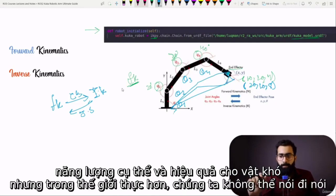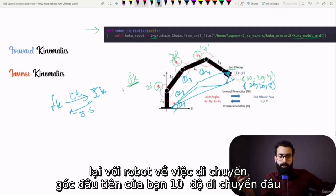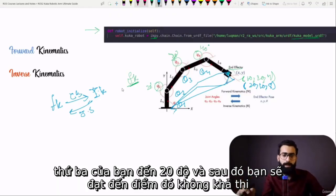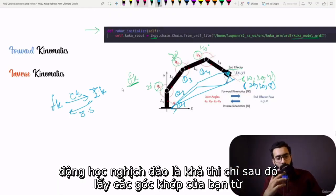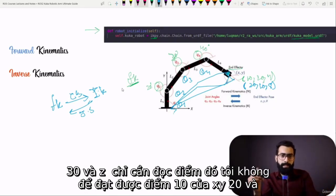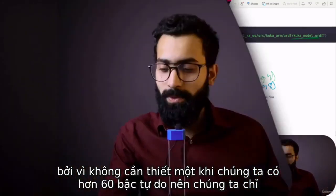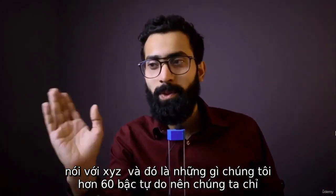Inverse kinematics is the hard thing. But it is more real world. We cannot tell the robot again and again to move your first angle 10 degrees, move your third angle to 20 degrees, and then you will reach that point. That's not feasible. Inverse kinematics is feasible. We just tell it, take your joint angles from your inverse kinematic solution, and make the end effector reach point 10 in x, 20 in y, and 30 in z. Just reach that point. I don't want to care about all of the joints, because in redundant robots we have more than 6 degrees of freedom. So we just tell x, y, z, and that's what we would like to have.